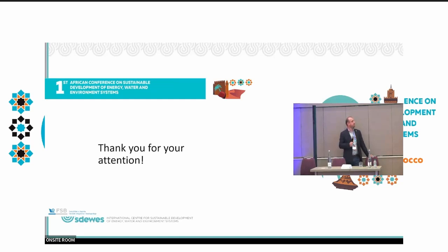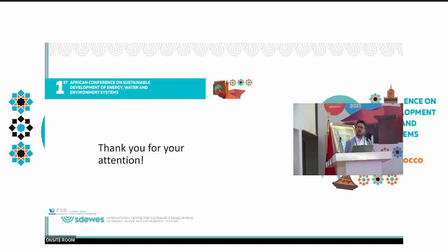Well, first of all, you need to have very good building codes in place. That means you have to be very strict in defining what can be built from an energy consumption point of view. So you have to be very strict in defining, let's say, maximum useful heating energy per square meter. If you're building a new house, it has to be less than 20 kilowatt hours per square meter. And this is like a prerequisite of everything. If you want to start building efficient systems, then the first step is actually to build buildings in a very efficient way, so they really consume a low amount of energy. And when you have that, then you can discuss different kinds of technologies that will help you go from this useful to final level with different technologies, efficiencies, and so on.